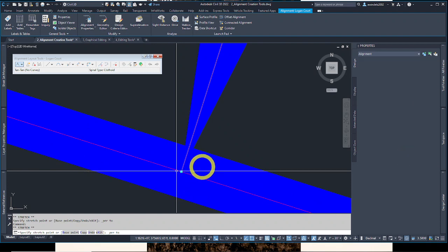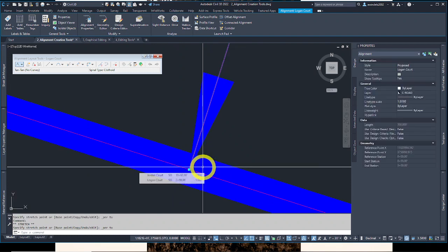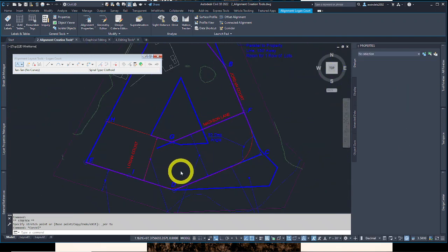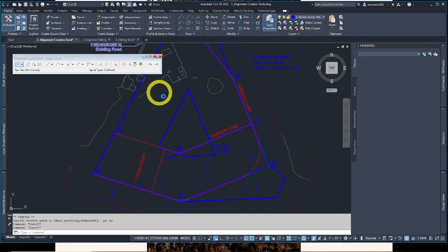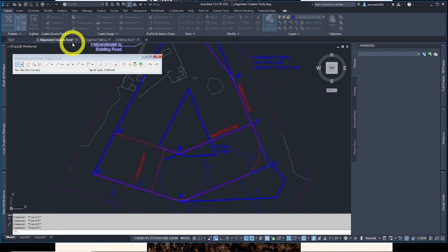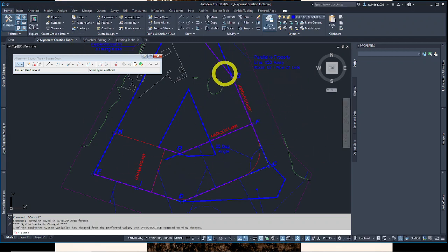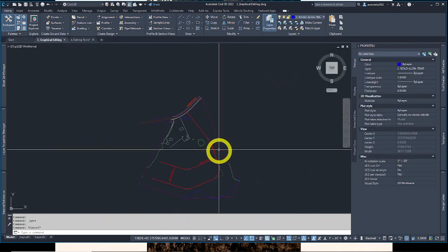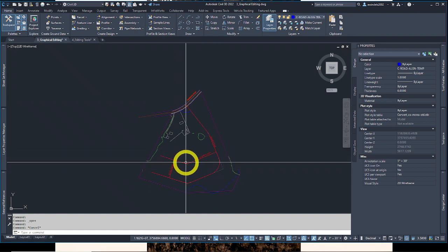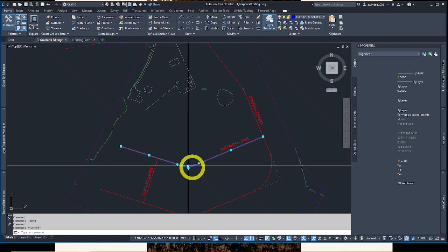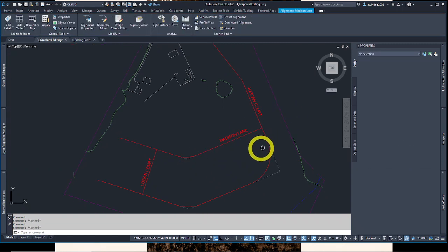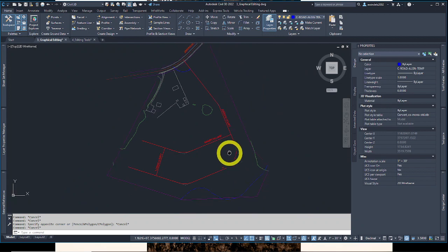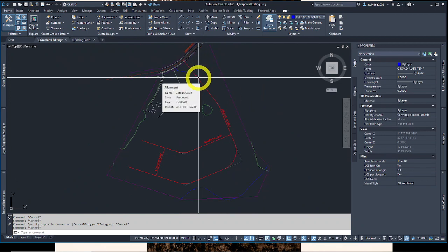Okay, it's all good. So we're going to page 98. That is it on that. It's just saying we're laying out our first alignment. I'm going to close that. I'll say yes. Just save that for now. We're going to go to graphical editing next. So this is getting us to use temporary geometry that's drafted in a certain way to start building our alignments, snapping to, which we just did. And you saw it. I didn't add this bad boy because I didn't like having a curve here to start, but we're using polylines and various geometry I had in the drawing already to help me build my initial alignment, and that's not a bad thing.